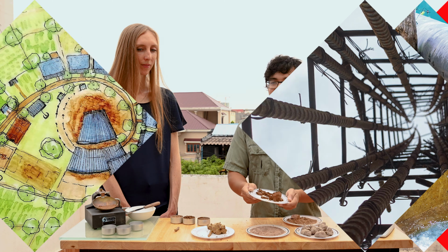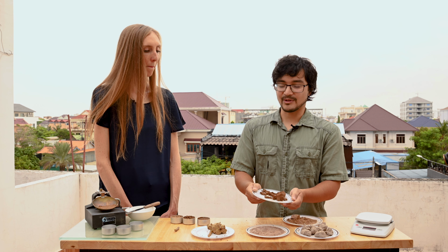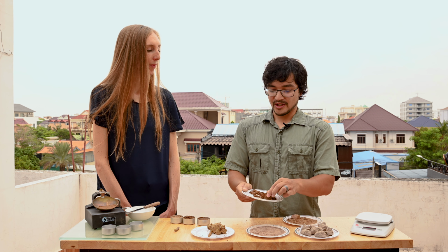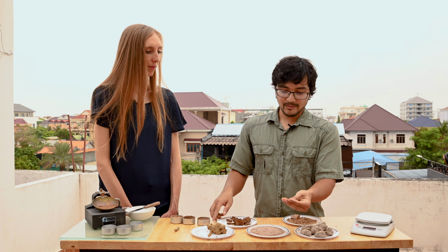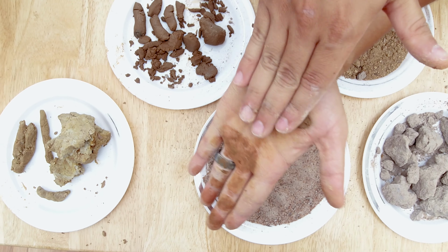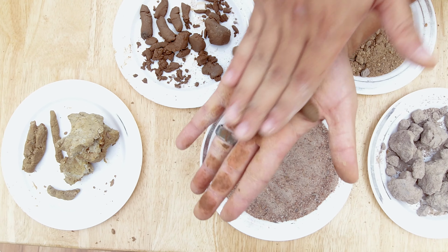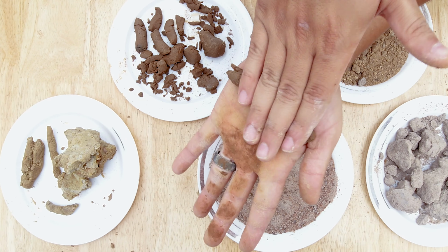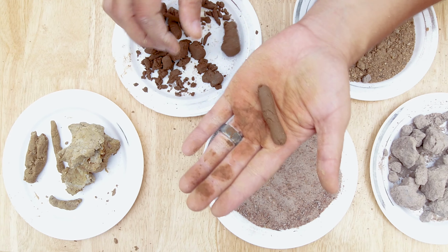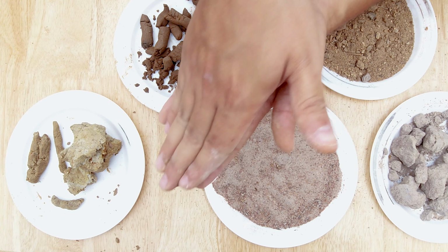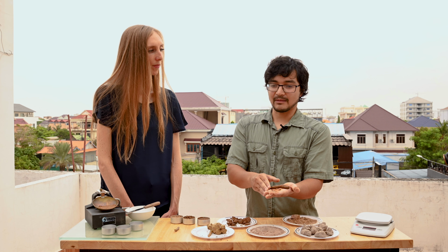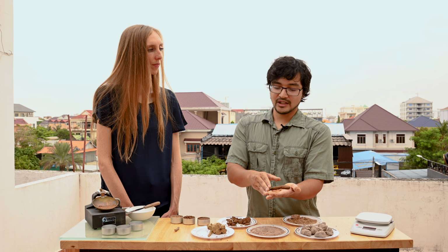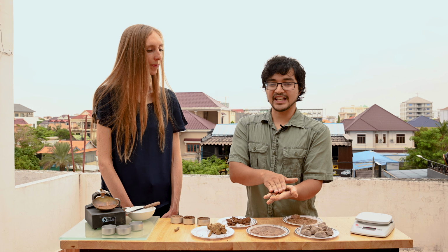For fine-grained soils, classifying the soil type is a little bit more difficult and requires more experience. So you'll begin by taking your soil sample and attempting to roll it into a thin thread. So for fine-grained soils, you'll begin by trying to roll it into a 3 millimeter thread, which we would classify as the plastic limit. The plastic limit is the point at which the soil changes from behaving like a plastic with high moisture contents to a solid at drier moisture contents.